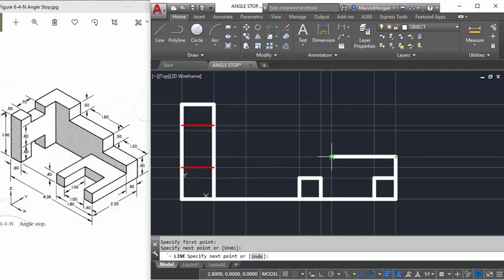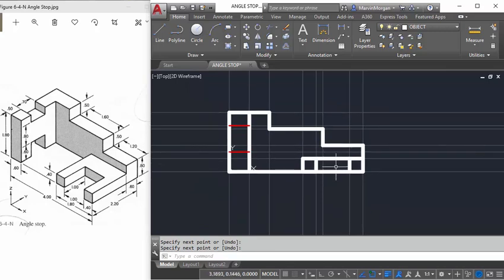Now I'm going to go over to do my 120. Next would be to go up 50 units. Then I'm going to travel over another 160. And then up again. And then I'm going to close it off right here. So that creates pretty much the back wall with 3 steps here. I need to draw one more line from here to close off that section. And that ultimately completes the front face of this object.